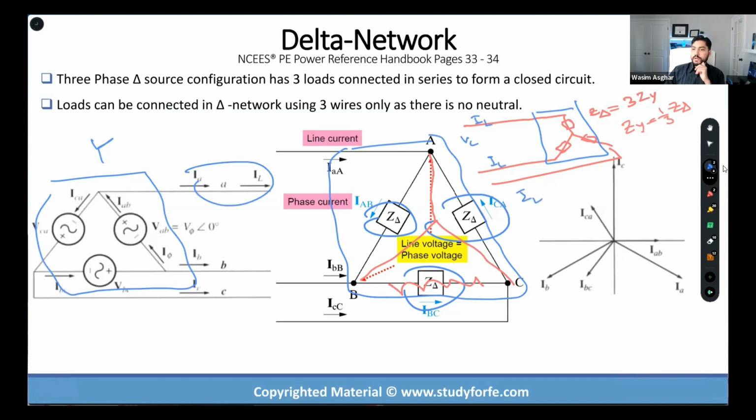And that is the reason why we love line quantities in three-phase systems. Because I'm doing these modifications on the terminals, right? On the source terminal and the load terminal. I'm not doing any changes on the line parameters. That is why, when we're dealing with three-phase systems, guys, if the voltage is not mentioned, by default it is considered to be the line voltage, right? These remain constant.